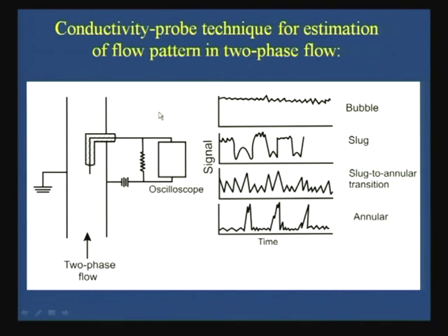The first thing is it's cheap, and it has an instantaneous response. Moment the bubble touches, there is a drop in the voltage, and again when water touches, there is a rise in voltage. So, the response is instantaneous. This is one good thing about the conductivity probe technique. It is simple, hazard free, all those advantages are of course there.